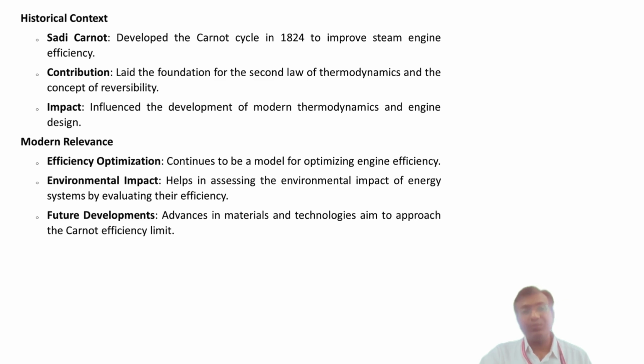Now, looking at the modern relevance of the Carnot cycle, in contemporary times, the Carnot cycle remains a cornerstone of thermodynamics and engineering. It provides the theoretical upper limit for heat engine efficiency, calculated by 1 minus Tc by Th. Engineers use this limit to evaluate and improve the efficiency of real-world heat engines such as internal combustion engines, steam turbines, and gas turbines. For example, in a power plant, the difference between the actual efficiency and the Carnot efficiency highlights the potential improvements.